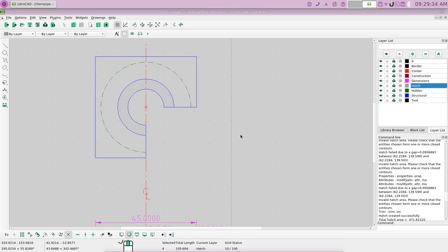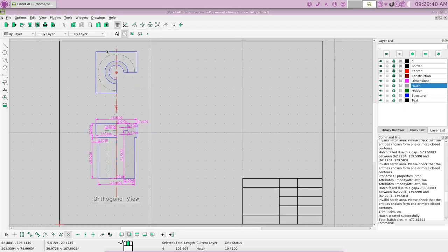Okay, so now if we zoom back in with auto zoom, you will see this is what that unit actually looks like. Okay, here's your hidden lines here. Hidden line detects this diameter, and this line detects this diameter that you're actually seeing from here.